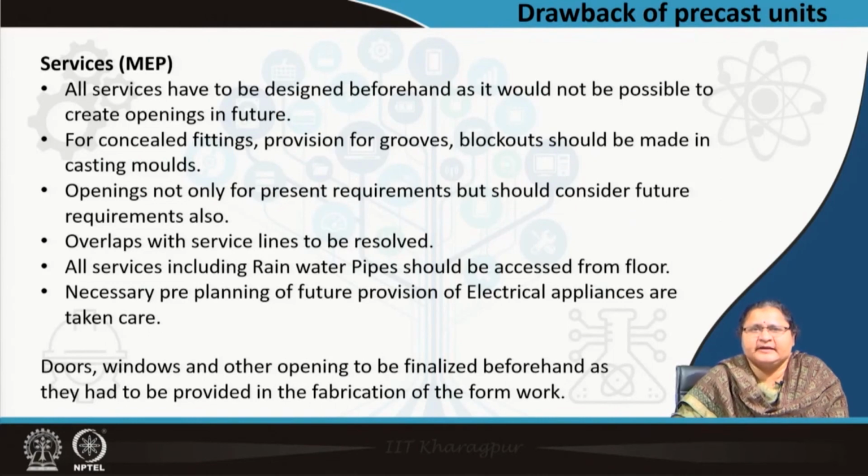All mechanical, electrical, plumbing together is usually called MEP. The MEP services have to be designed beforehand, as it would not be possible to create openings in future. Moreover, any expansion program should be considered. So, any future planning should be incorporated as concealed fittings, provision for grooves, blockouts should be made in the casting mold. Openings not only for present requirement, but as I told, for future are to be accounted.